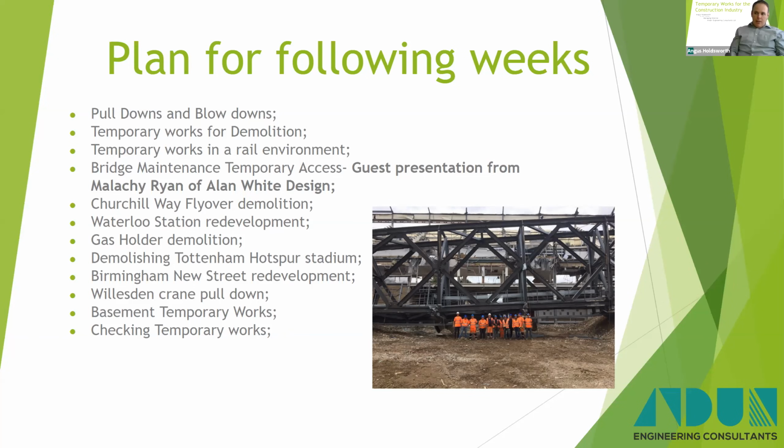But I think scaffolding around buildings when they're being demolished is here to stay for a while at least. So it's down to the demolition contractor and those planning the demolition to make sure that the structure can be demolished in a safe means with the scaffold in place. And if they can't, then they need to come up with another solution. But a scaffold can never be relied upon to prevent a building collapse. Hopefully that answers the question, or at least gives you my thoughts on the question anyway.